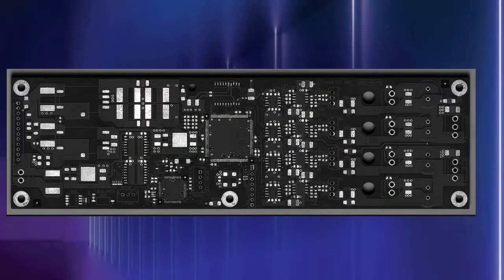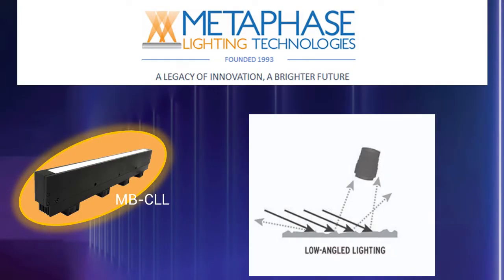In these low-angle lighting applications, the incidence angle is acute and the background surface appears dark as the light is reflected away from the camera lens, while irregularities are reflected into the lens and appear bright. The Metaphase MB-CLL uses proprietary optics to project its light at a lower divergence angle. This helps keep a tight, structured beam of light at a longer working distance, even many meters away, while delivering high intensity. The MB-CLL works great for applications where you can't have the light close to the object or web.